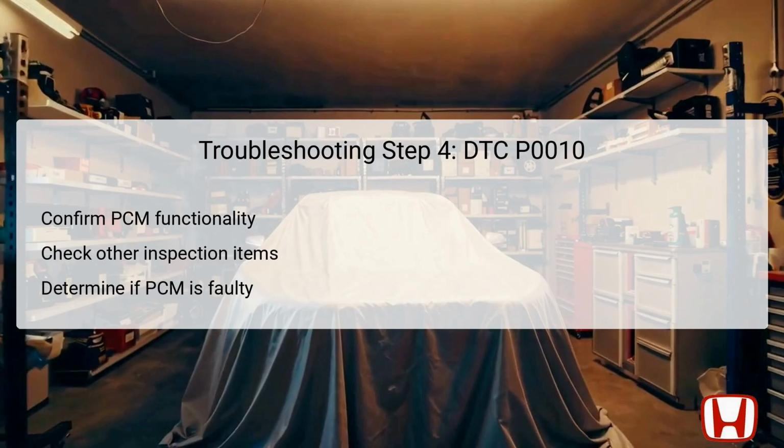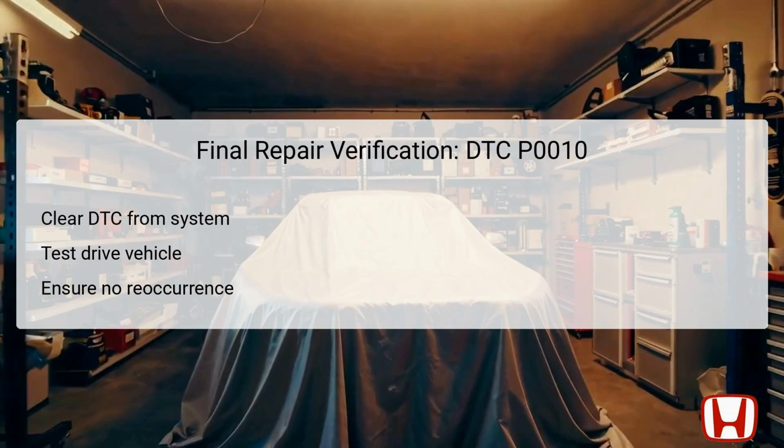Technicians will utilize diagnostic tools to verify if the PCM is performing its duties correctly. If abnormalities in functionality are discovered, such as failure to execute commands properly, this indicates a problem with the module itself. Depending on the finding, further actions may include reprogramming or replacing the PCM to resolve the issue and restore the vehicle's performance.